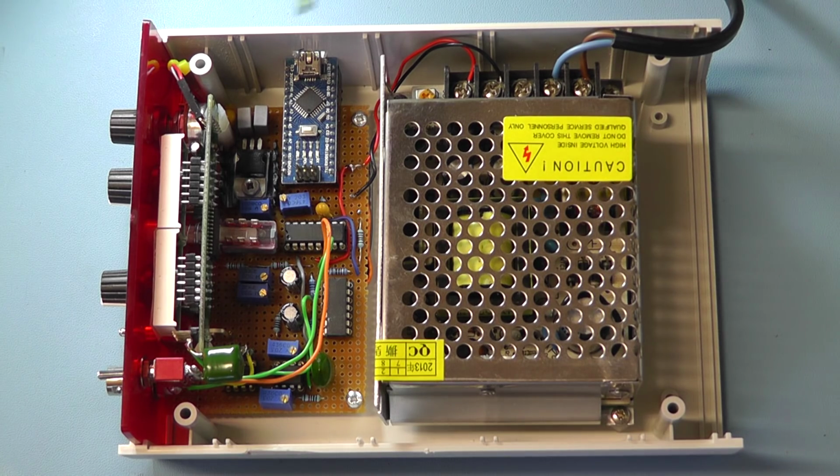Right, well here you can see now I've got everything boxed up. The board is firmly fixed in the base of the box, front panel on, the 12 volt switch mode power supply is bolted onto the bottom of the casing using plastic spacers to make sure it's safe and isolated, and then I'll probably take the mains cable out through a rubber grommet on the back panel. You could even add an on-off switch if you wanted on the rear of the box.